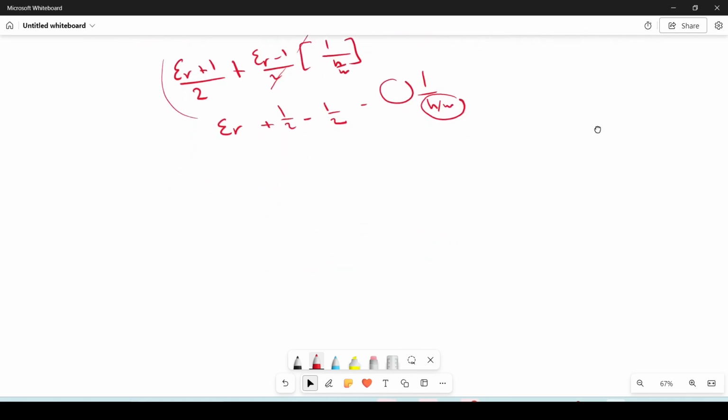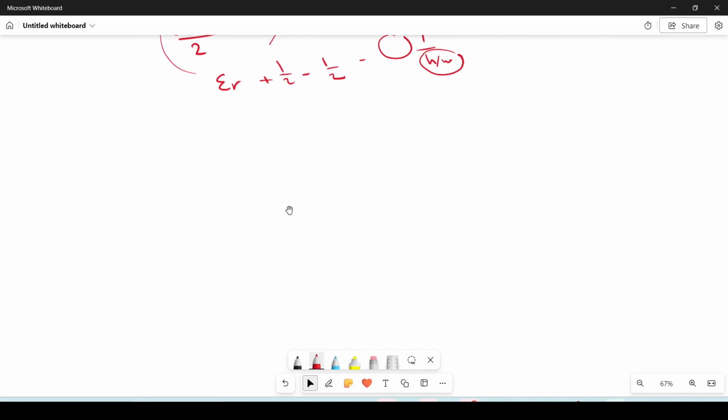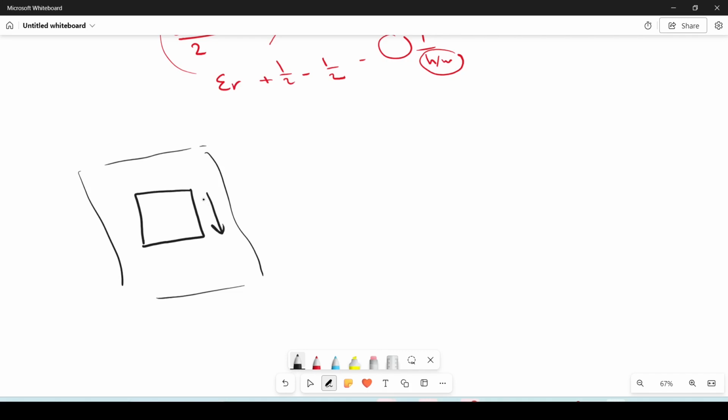So to summarize it, we have a patch antenna, right? And we know that it represents something like a cavity that is controlled by the dimension L1, for example, and L2. And we know that once L equals lambda over 2 of the frequency we want, we have a mode over this edge. So in the typical patch antenna, we want just one mode. So usually we choose one of the edges. For example, I will choose these two edges to be radiating.